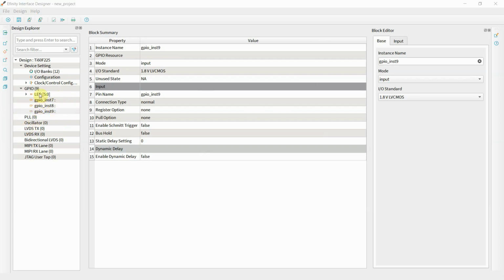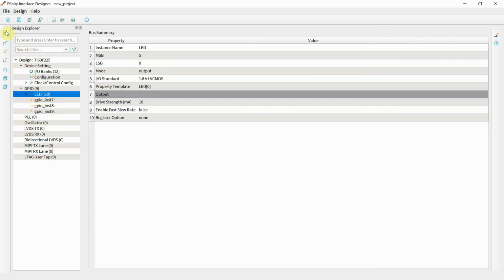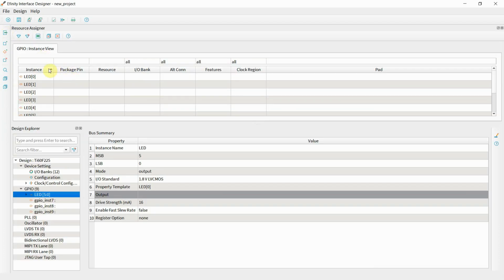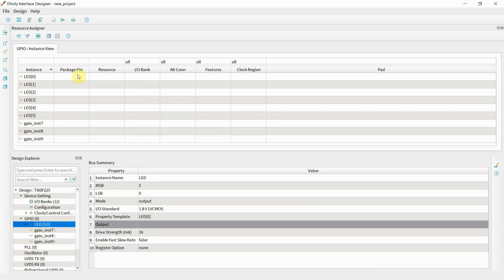Before we change the name here, we go back to the LEDs and go to the resource manager. And now we see our defined pins. And now we can assign them to the package. For example, starting with LED 0. And if you look to your PDF file or in your VHDL file, you will see that LED 0 should be connected to K14. So now we are looking for K14. It's here. And press return. Then all the other fields will be filled up.